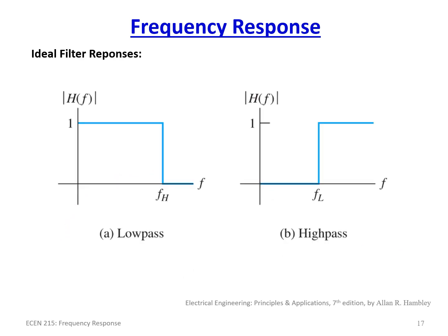So, okay, now that we've discussed these actual transfer functions, just to sum everything up, we have these 4 different filters. Ideally, graphically, it looks like this. Ideally, you would have the magnitude of a low pass filter be 1 up to your cutoff point, f of h in this case, or f of c, and then after you hit that point, it is completely 0. So it is like a square function up to the moment of the cutoff frequency.